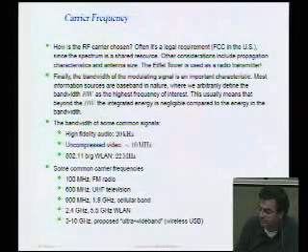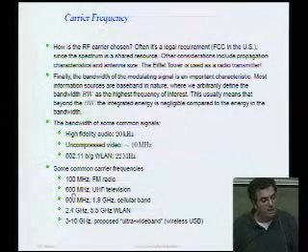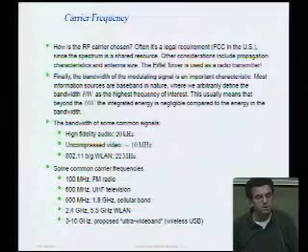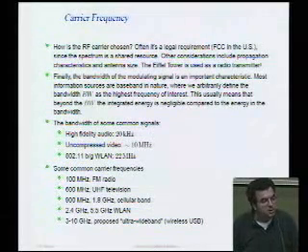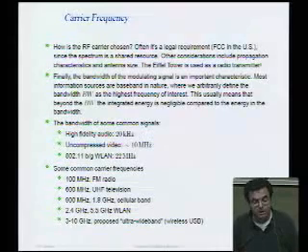An example of a spectrum that people would really like to go after is this UHF spectrum. And the reason is that UHF is probably one of the sweet spots in the spectrum in the sense that you can get very good long-range transmission with reasonable antenna sizes. It's very good at bending corners and going through trees and walls and whatnot. And frequency is still low enough that you can build very low power circuits. So it's almost like an optimal frequency for building, let's say, wireless internet.